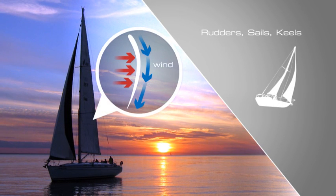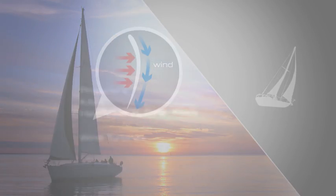Air moving across the outer convex side of the sail has a longer distance to travel in the same amount of time as air moving across the inner concave side. The air on the outer side is traveling farther in the same amount of time and has a higher velocity or speed than the air on the other side. This higher velocity air has more room to spread out, forming a low pressure area. On the inside of the sail, the slower moving air is packed together more densely, creating a high pressure area. This difference in the pressure on the sail acts as a forward suction or vacuum, producing lift.